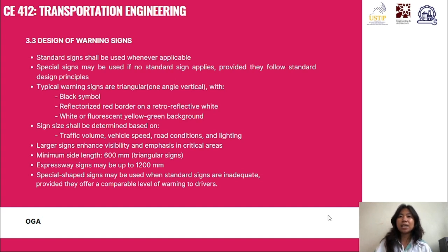So the appropriate size of a warning sign is influenced by several factors, including the traffic volumes, vehicle speeds, prevailing road conditions, and background lighting. If a situation requires greater visual impact or emphasis, larger signs should be utilized along with proportionally larger symbols or legends.